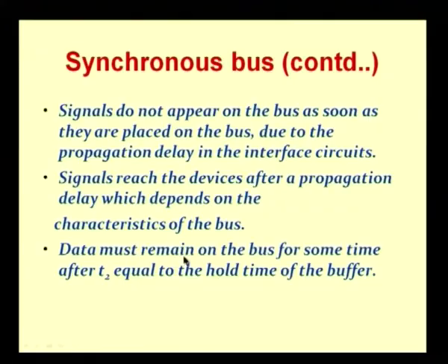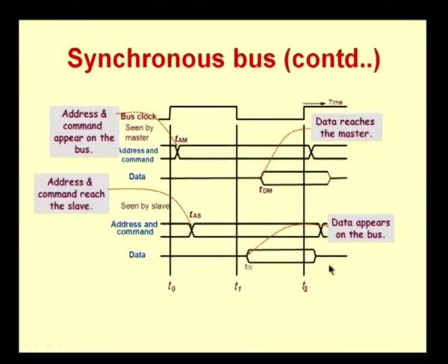Okay. And data must, as I said, remain on the bus for some time after T2, which is equal to the hold time of the buffer. So we have the setup time, which is the time before the clock that the data should be there, and the hold time, which is the time after the clock for which the data should be available. Only then can you make sure that the data is successfully written into the buffer. Okay. So these are the things that we need to keep in mind with respect to the timing for the synchronous bus. Okay. So you can see all these things captured in this figure over here.